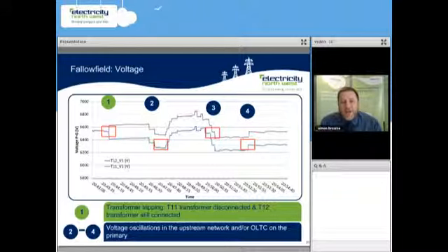The Siemens ASC at point 3 then took action to reduce the voltage level back down to the 5% level. So again, you can see at 3 that the voltage level has decreased. Point 4 is just showing the normal fluctuations that you get regarding the amount of demand you have on the network. So the voltage level is always changing. You're never going to have a smooth voltage curve, and that's what makes it quite awkward for Manchester University to tell what actual response you are getting pre and post these trials.